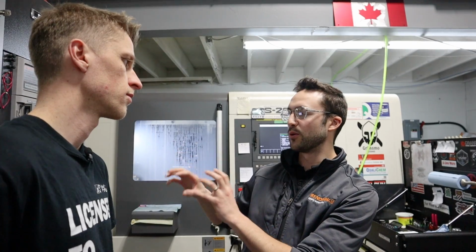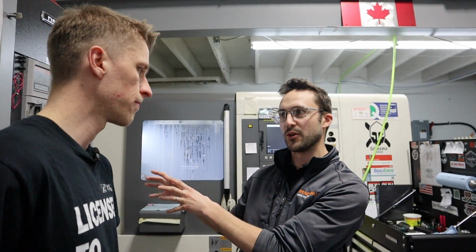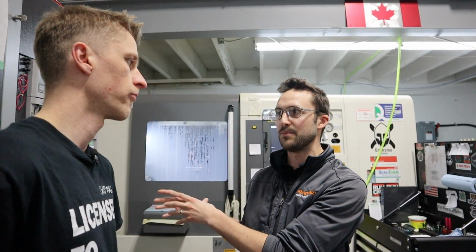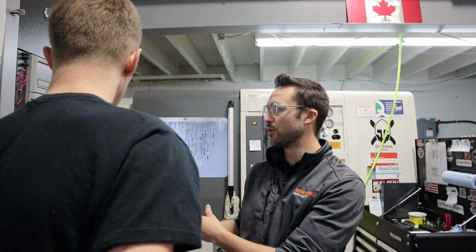If you have a data server option, that means you get to store all of your outputs or your programs on the controller, and it acts as its own FTP server. The alternative is having that on an external computer, so you can push and pull programs, but also send out printed reports from probing automatically to the server, available to any computer attached to that server. Yeah, that's right. Everything on your main network from wherever you're working.